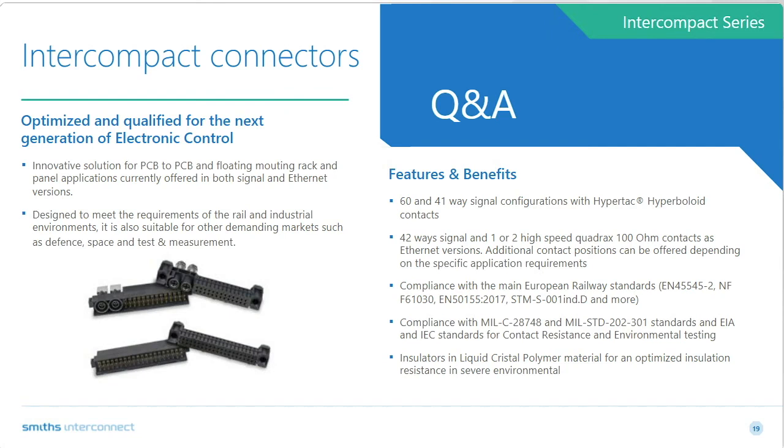There are quite a few areas that I want to highlight. To start with, I want to draw your attention to the contact design. In the case of the hyperboloid contact, I talked about the high reliability under shock and vibration, its immunity to fretting and corrosion, and the low mating forces, all of them combining to give the main objective of stable contact resistance.